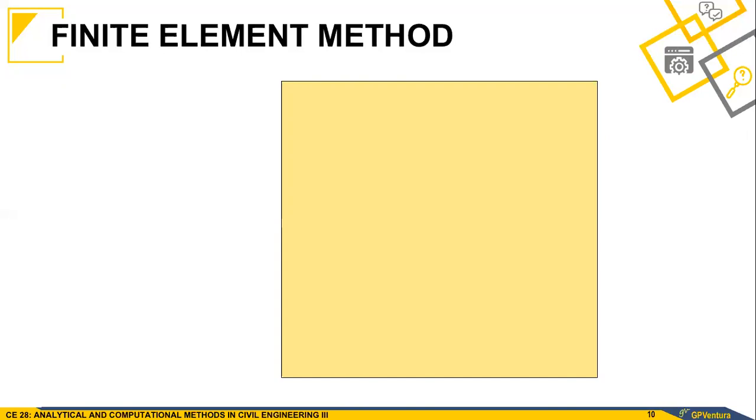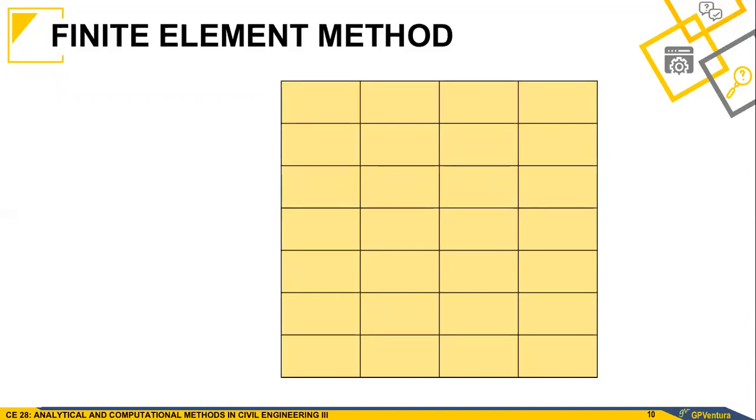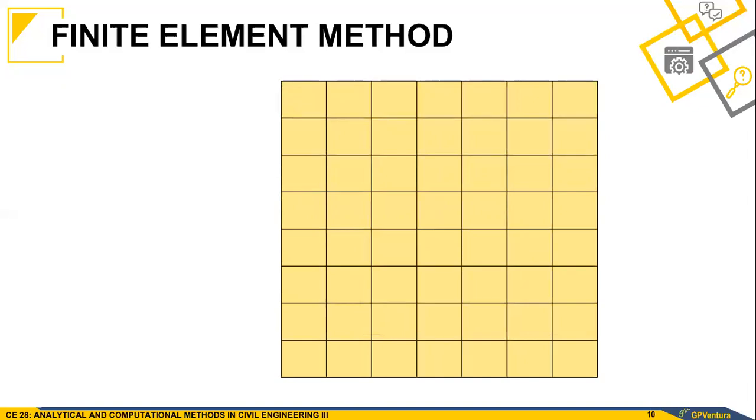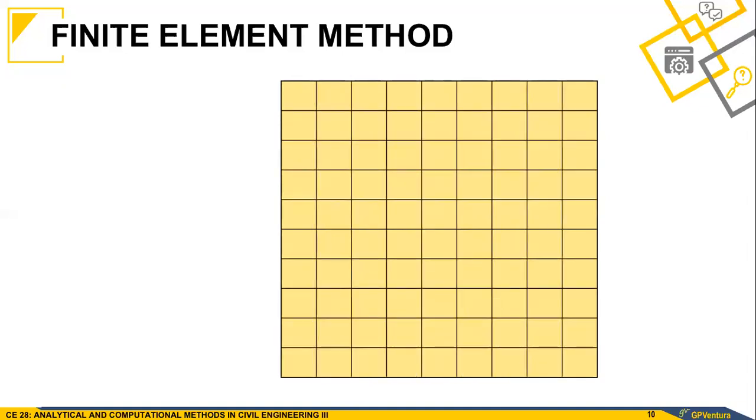My first step, as we have mentioned, is to discretize. Okay? So I have subdivided the model into several elements, but then again, what I can do is I can refine the mesh even more, okay, for my elements to be smaller and for me to have more accurate results. And even further, what I can do is make an even more refined mesh.